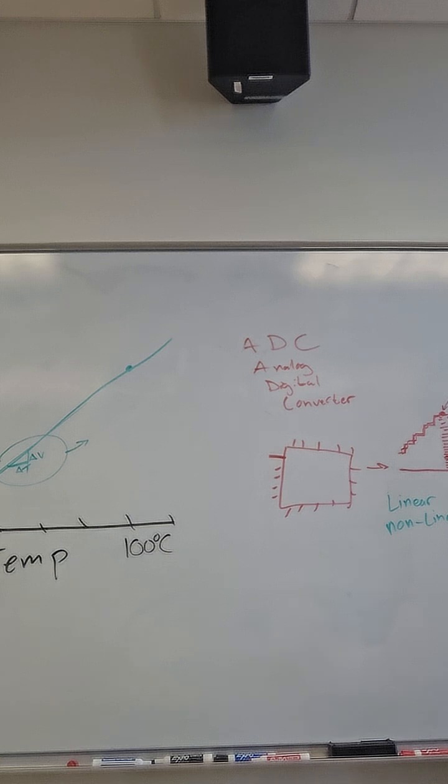When you have a sensor, whether it's pressure or temperature or humidity, you'll always kind of have to go through this. You have the raw reality of the sensor type, digital output or analog output, and then it's going to be digitized. So you're going to bin it between 0 and 255 or 0 and 65535, right? And those steps mean something. Then you would have to look up in the data sheet how much voltage change means how much of that characteristic, right?